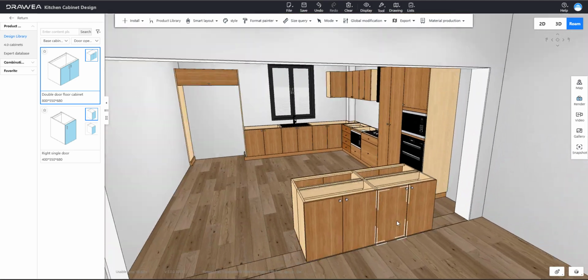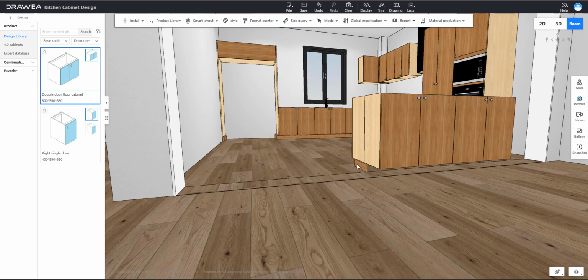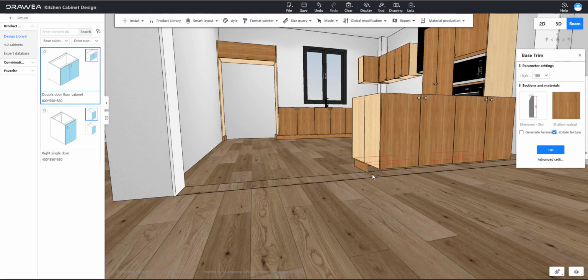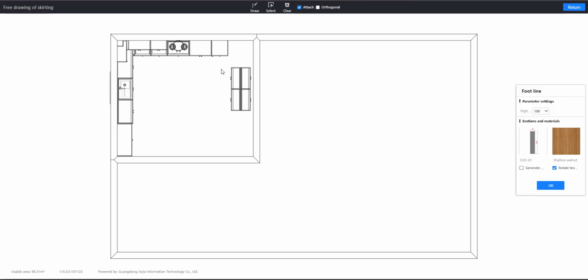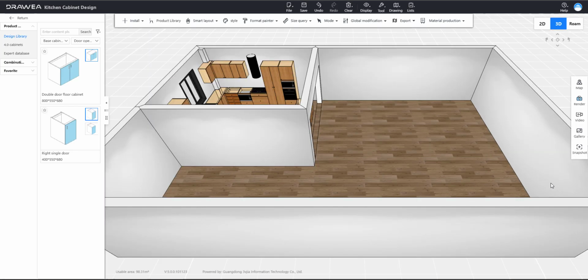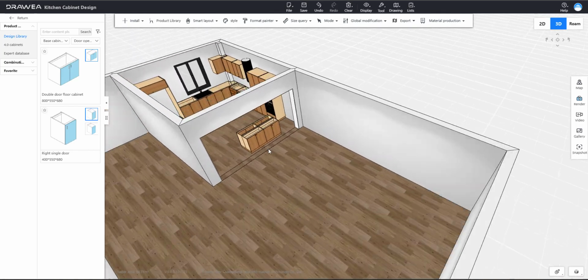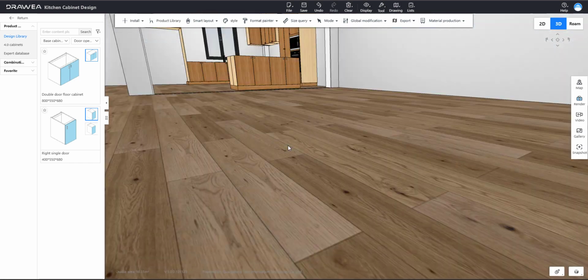We have a section here that is not formed. I am showing the method for our areas that are not formed in this way. Base molding, base trim. From here I chose the draw option. The lines I want from here and again the cross section that I want to apply. By determining on my shape, I select the material and press OK. As you can see, this is how the base trim section was created.